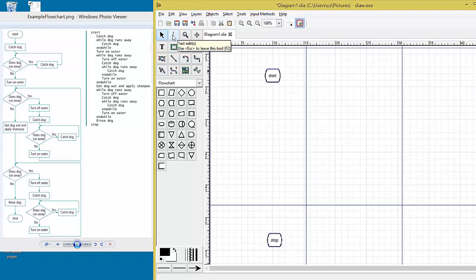Now, if you make spelling mistakes or you need to change or edit the text within the shapes, you can click on the text editor and then click on the shape itself, and then you're going to see the insertion pointer is enabled, so you can add or remove text from the shape. As you are typing, the shape gets wider, and you can see that after I remove the text, the shape did not shrink back to the minimum size. So you can just select the shape and drag one of the handlers, one of the green squares, and resize the shape. Okay. You can always click on the shapes and just move them around as you need them. The default pointer is the arrow that actually moves the shapes around.